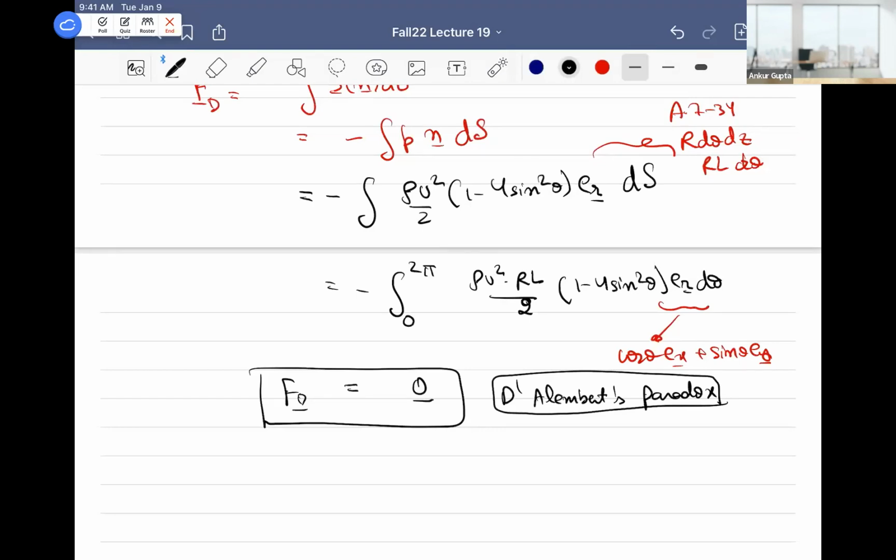Why do you think this is wrong? Well, it seems that the fluid flows perfectly over, so you get the pressure from integrating half of it, the same as the opposite of the other half. So it assumes that the fluid flows perfectly over it, but really you're probably going to get some kind of separation of that layer, right?